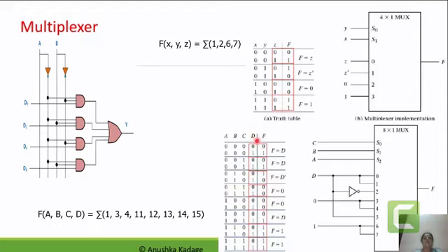In this case, the LSB bit, D, we are observing that it frequently varies, while ABC remains constant for two sequential input combinations. And that's why we will do the grouping where ABC first will remain constant. So accordingly we will find 8 different combinations in which ABC remains constant, but in that D gets varied. And that's why these 8 groups have been made.